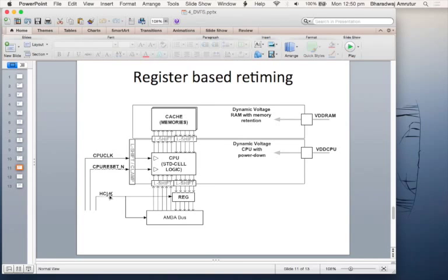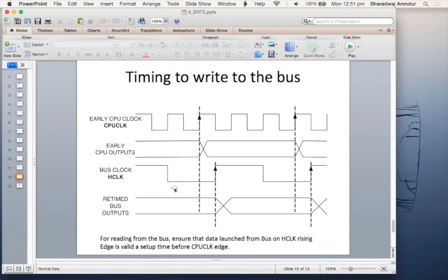When they are doing the design and generating the clock tree, they ensure that no matter what, even after going through the level shifter, despite the worst case skew, and no matter what the voltage level is, the CPU clock comes ahead compared to the edge clock. These are additional constraints you put. The reason they put these constraints in the design of the clock tree is that it makes their analysis and the rest of the design simpler. So that's the approach they take in this example.